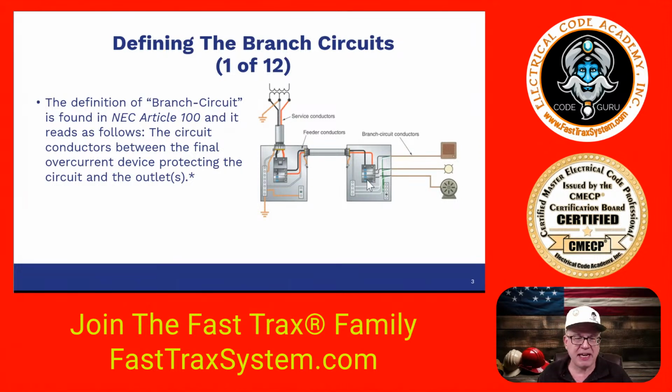Now, here we have individual breakers, and these are feeding these circuit conductors out to specific loads, like an outlet or a receptacle that is mounted in an outlet box. And a receptacle is a device, but the branch circuit could be feeding a motor, whether it's cord and plug connected or hardwired, and the same for a heating circuit. Same scenario. Could be a cord and plug heating appliance or hardwired. The main focus of us understanding what a branch circuit is in this layout is from right here. This is the last overcurrent protective device out to the outlet.